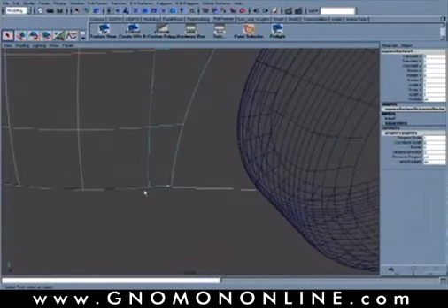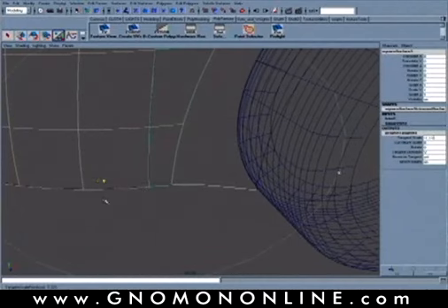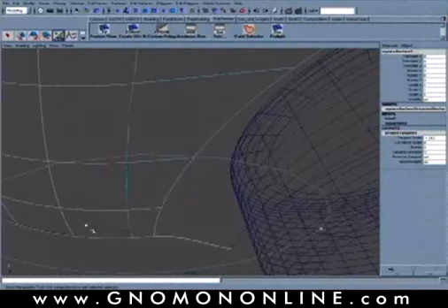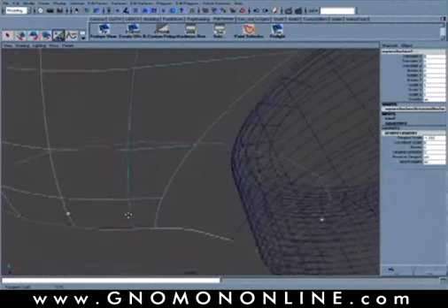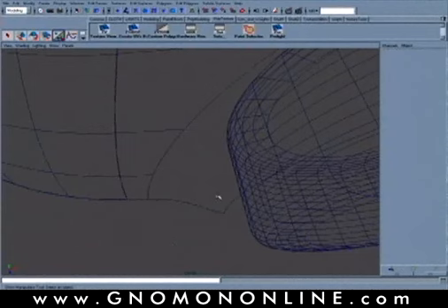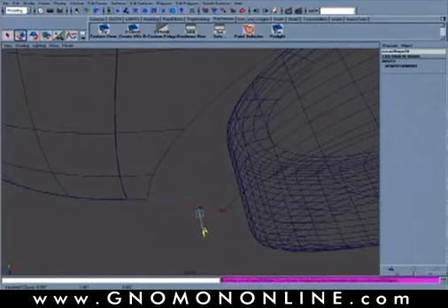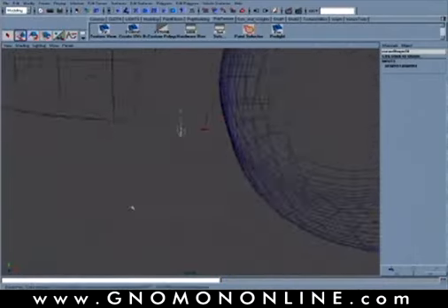So we can reverse tangency or hit our T show manipulator, scale our tangency to go in the opposite direction. Okay, so we're creating that smooth control for that second point away from the curve there. Okay, and then our other point we can grab with CVs, and if we want to just manually adjust it, maybe this flattens out towards the bottom here.